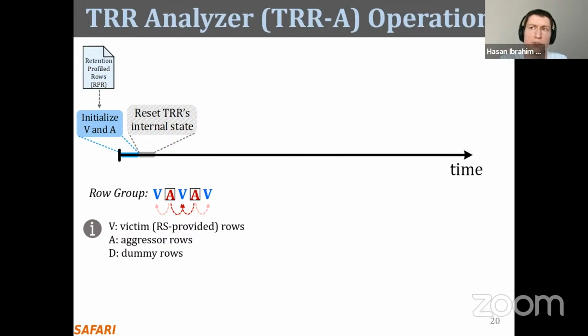Due to a previous experiment, the TRR mechanism currently has some rows registered as potential aggressor rows, and the user may not want these previous experiments to interfere with the current experiment. This reset step issues a lot of refresh commands and a lot of dummy row activations in order to clear that previous state with some dummy information.